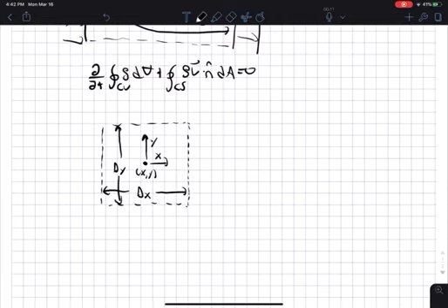Okay, and so we need a control volume. Here, we're going to be very careful, and we're going to define the mass flux vectors going through this as rho v dot n hat times the area at x plus delta x over 2. The reason for doing that is that when we do this type of analysis, we need to very carefully consider where each of these points are. This point here at the center of the control volume is at x, y, and the distance between the center of the control volume where we're going to find rho is delta x over 2.